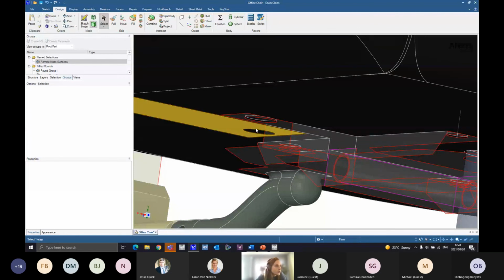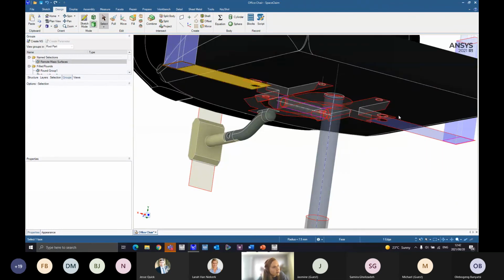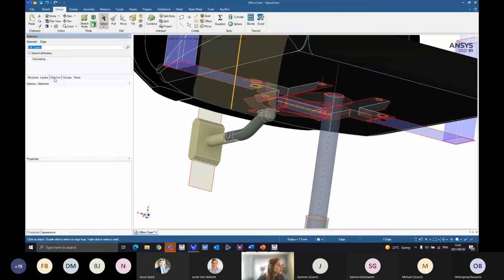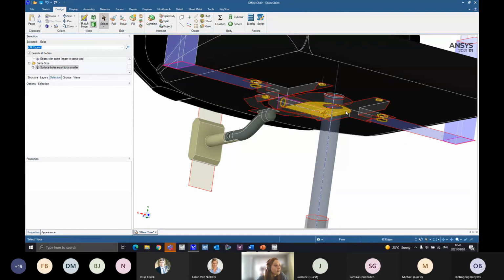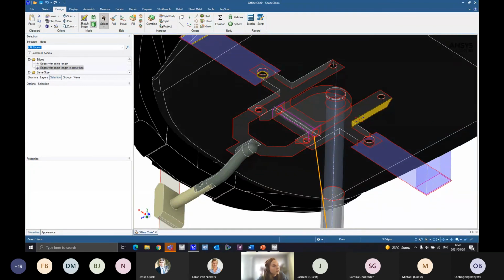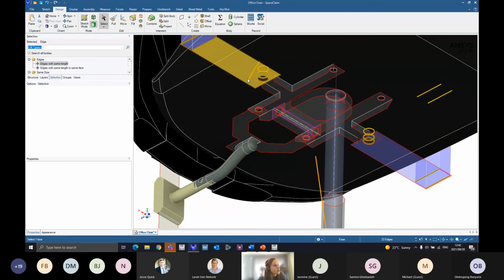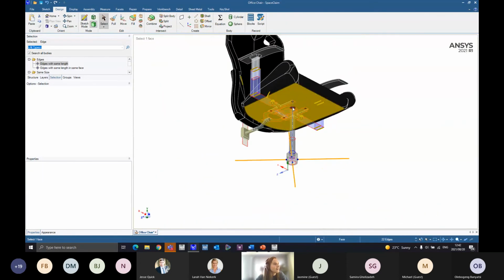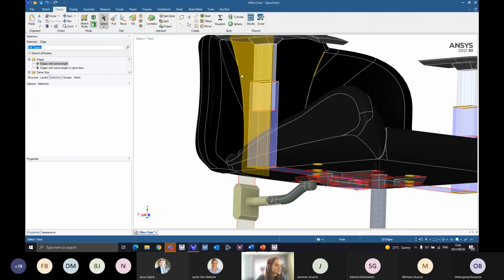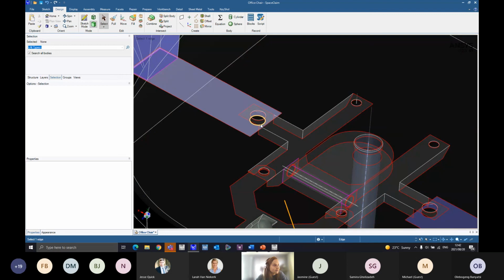So you can scope a face or an edge. In this case, I'm going to use an edge. So I'm going to start with the bottom edge there, but I'd also like to select this one. So you can use your power selection again to hit equal to or smaller, same length. Okay, so it's all bodies. Okay, cool. So in this case, it's actually selecting quite a few. That's interesting to think that that edge has the same length as this one. But it's usually a bit easier to do that.